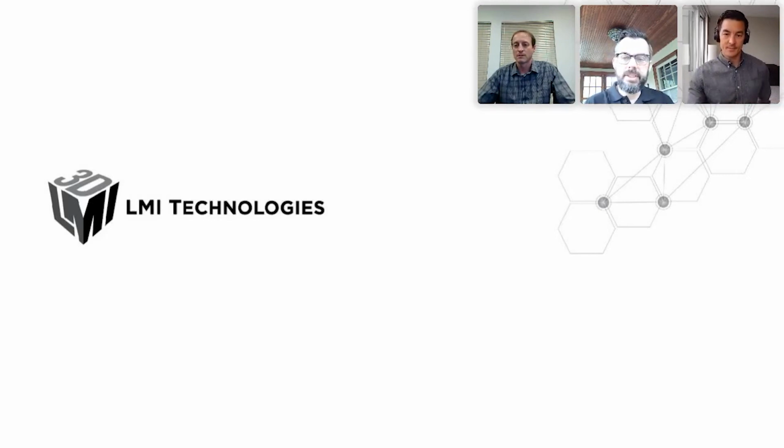Yeah, it includes the surface itself, and that's really important for the surface direction filter because one thing I want to remind everyone about the surface direction filter is you're telling it what to keep, not what to get rid of, right? So it's important that your ROI contains the surface that you're trying to maintain. In this case, it was that flat base.